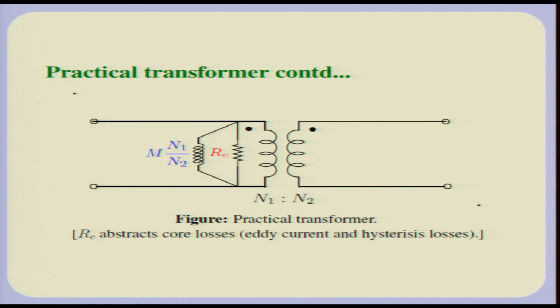You can look at it as, see, even if you assume that this second coil is not there at all. Okay. If you assume that this second transformer coil is not there at all, the eddy currents are like coils of current within the ferromagnetic core. Okay. So, the referred loading resistance can be represented here in this fashion. Of course, the value of this resistance is dependent on parameters of the core itself and the frequency. Okay. Now, of course, this represents a loss in the transformer.